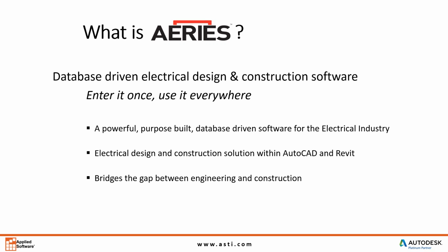It will push information, and it will pull information, extracting information from the models. So if we have a model, we can push the electrical equipment into the database. Then we can use the Aeries database to help us with the cable sizing. It will help us with the cable routing, and also make sure that we have the proper size raceways in there when we model our raceways. And so it's a very intelligent tool in that aspect.